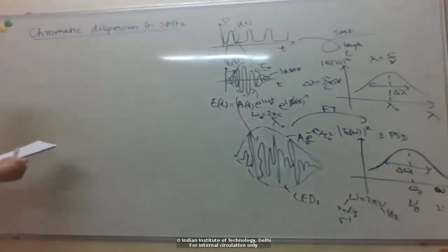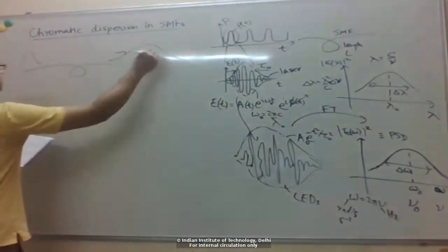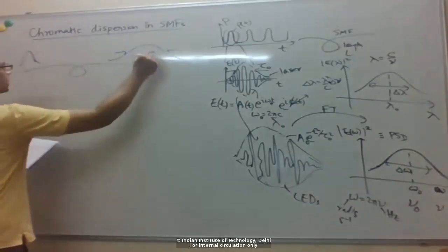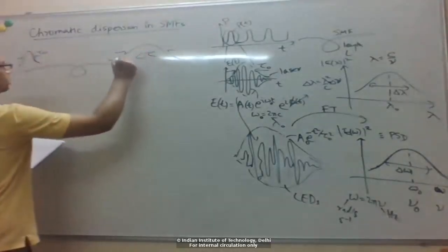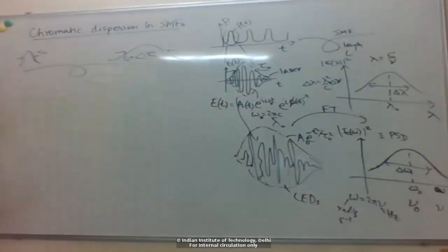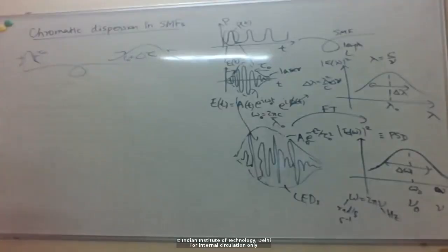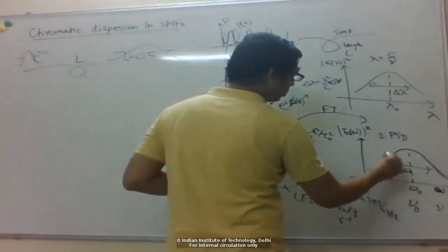So in this case, we want to see this thing, some pulse here broadens by an amount. So we send some tau naught, and so here the pulse width becomes tau naught plus some delta t broadening. Okay, so there's some fiber of length L. So if we take one particular frequency component here, out of this spread of frequency, let's just take some particular frequency omega.